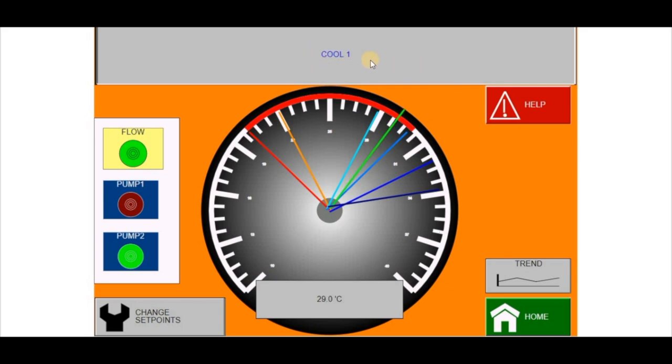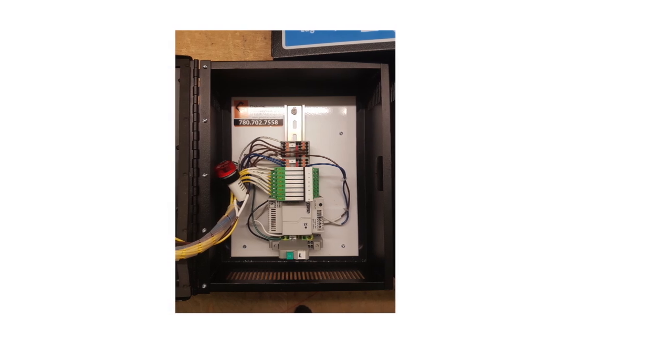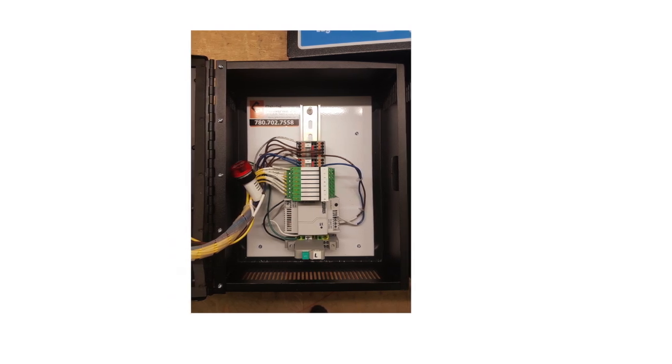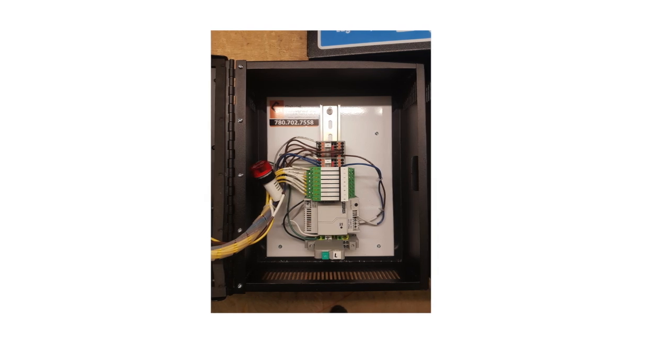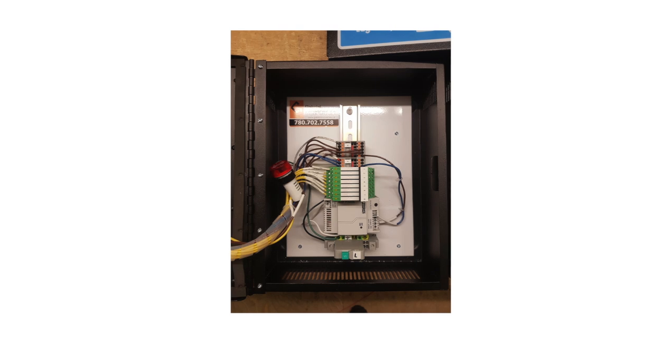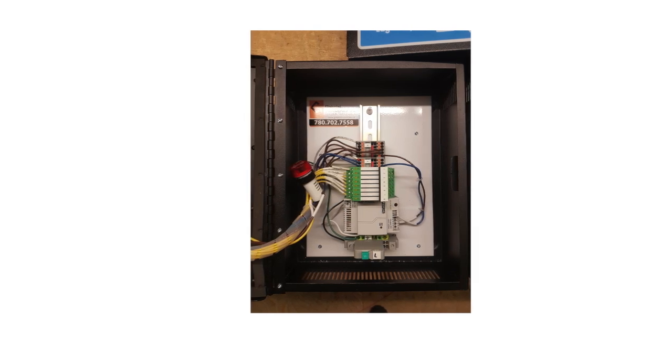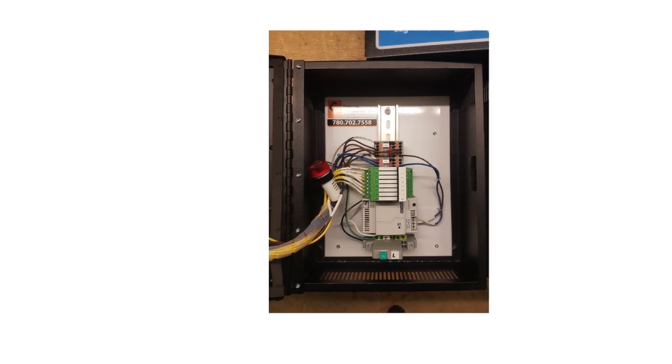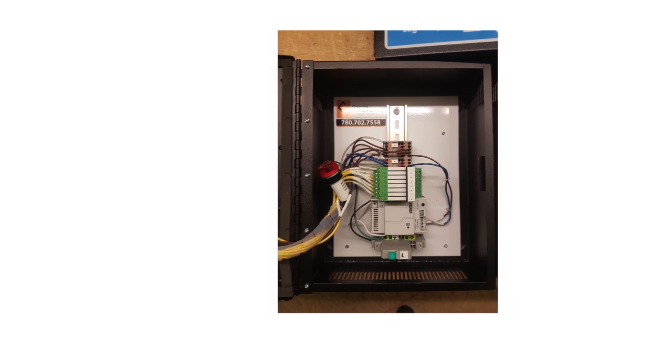Each system is different, and each stage is going to control a different function that is customized on a case-by-case basis. Typically, these stages will enable a pump or motor or heating or cooling unit via a relay located in the Flex panel. The Flex panel can also provide PID control utilizing variable signal outputs for a more in-depth control over the system.